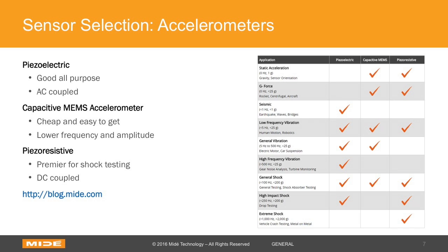And it's something that gets lost on certain customers that I've talked to repeatedly. As they see accelerometer, they expect to see that 1G offset when it's on a desk, for instance, to show the gravity vector. But a piezoelectric one does not have the ability to measure the gravity vector. For some applications, that's actually good. It's a form of high pass filtering. But for some applications like human motion, for instance, you'll want that DC coupling so you can measure gravity. Capacitive MEMS accelerometers are DC coupled.